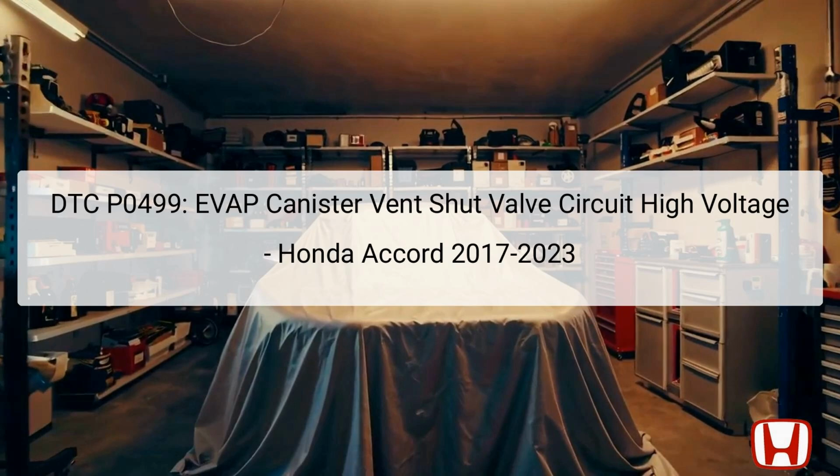The EVAP system is crucial for reducing vapor emissions from the fuel system, preventing environmental pollution. It works by capturing fuel vapors in the canister and routing them back to the engine for combustion. When the DTC P0499 is triggered, it signifies that the valve responsible for venting these vapors is malfunctioning, typically due to excessive voltage within the circuit. Understanding the components involved and performing a systematic troubleshooting approach is vital for accurate diagnosis and repair.